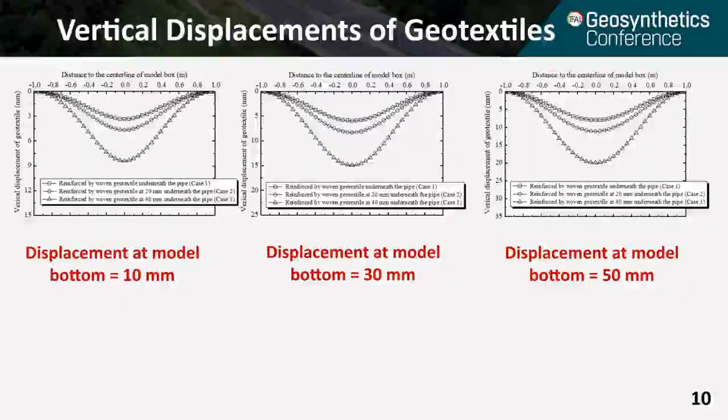This slide shows the vertical displacement of the geotextiles, basically when you have different maximum displacement at the model bottom. Okay, so that is the same trend as what we had for the vertical displacement of the pipe. But you can see, when you reinforce the pipe at the pipe bottom, the vertical displacement of the geotextile also had the minimum value.